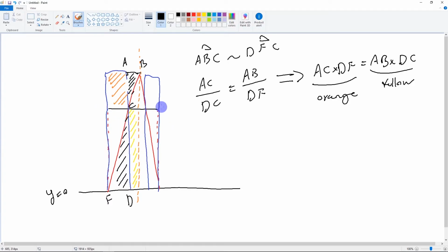Basically, the area underneath the signal is equal also for the triangular one. The PWM produced by the triangular would have also the same area. So we can see that this condition is fulfilled. And remember that I didn't consider anything related to the height of this signal. So whatever that height is and whatever the height of the carrier signal is, these equations are correct.